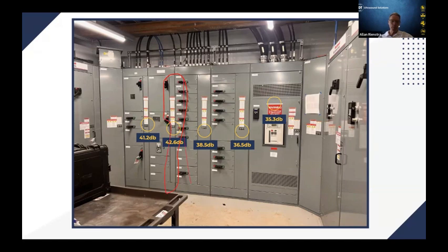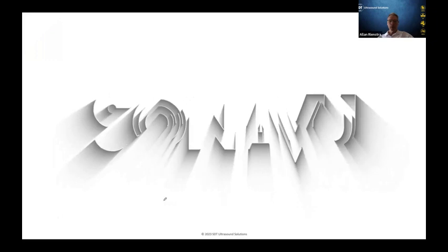So we'll open these up, and then of course we're going to suit up and put our arc flash and our PPE on before we open this up. But once it's open, now we can do some infrared thermography. Maybe we'll find something, although heat is a little bit later in the failure curve than ultrasound. But once it's open, again, from a safe distance, we can also listen and hopefully hear exactly where that buzzing corona discharge was coming from.